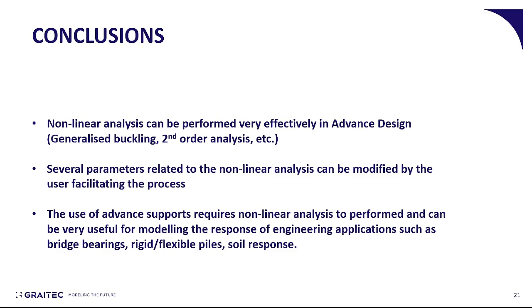We saw earlier that the user can define the numerical scheme used, can change the number of steps and iterations when running a nonlinear analysis. They can even change the parameters that are related to the convergence of the algorithm and the stabilization of the entire numerical scheme. And finally, the use of advanced supports requires nonlinear analysis to be performed and can be very useful for modeling the response of engineering applications, such as the bridge bearings, rigid and flexible piles, soil response.